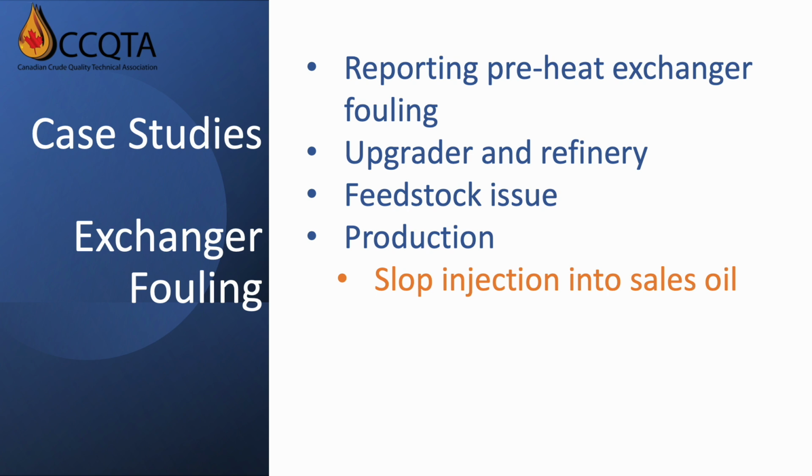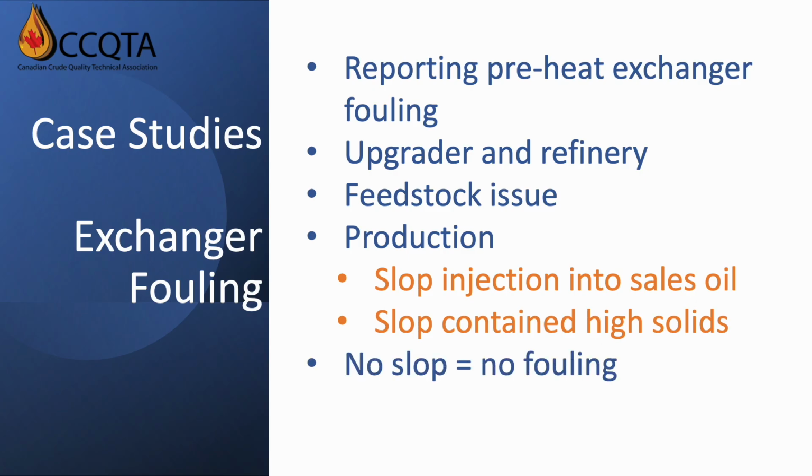They began an evaluation of a production facility directly upstream. The water from the separator went into a skim tank, and the slop oil from the skim tank was injected back into the sales oil going to the refinery. On testing, they found the slop oil contained a significant quantity of insoluble solids.